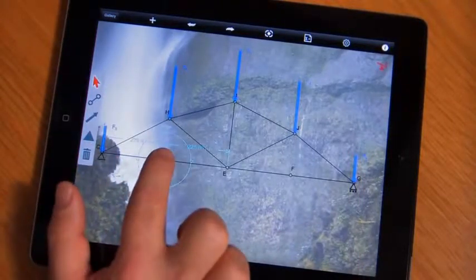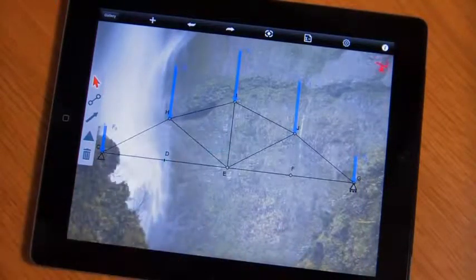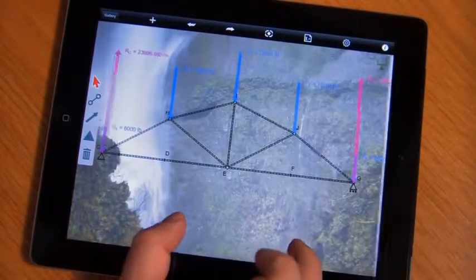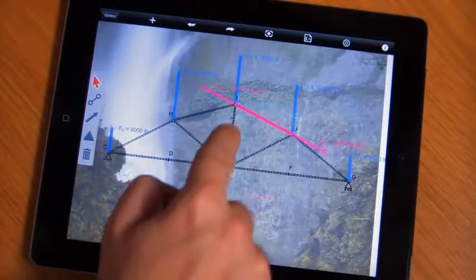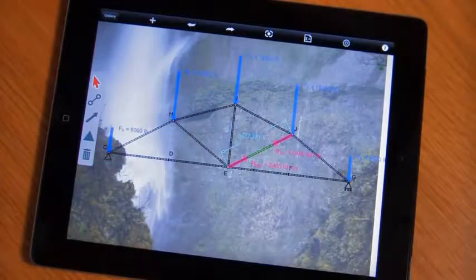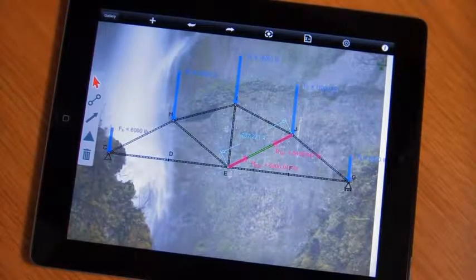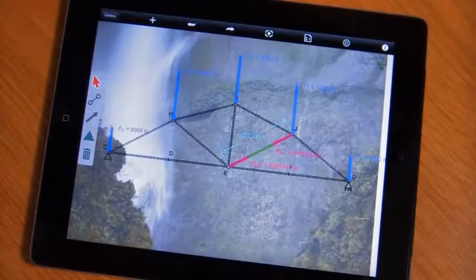Now we need to go in and add weldments here. We can turn these into single elements, and that should put us back into a solvable state. Now if we go back and start interrogating, we can see that we still have the 5,400 pound reaction force across J, suggesting that those members were redundant, they can be removed from the system, and we just reduced our cost in the design.